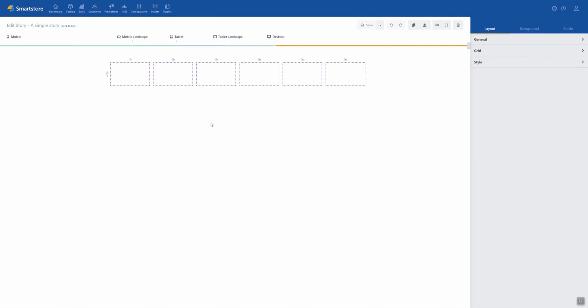First of all, we have to define our grid. We only need 2 rows and 2 columns for our grid. To add another row, we use the grid tools which become visible when we hover the mouse over the edge of the story. Here we click on plus. Now we remove the unnecessary columns also with the grid tools.